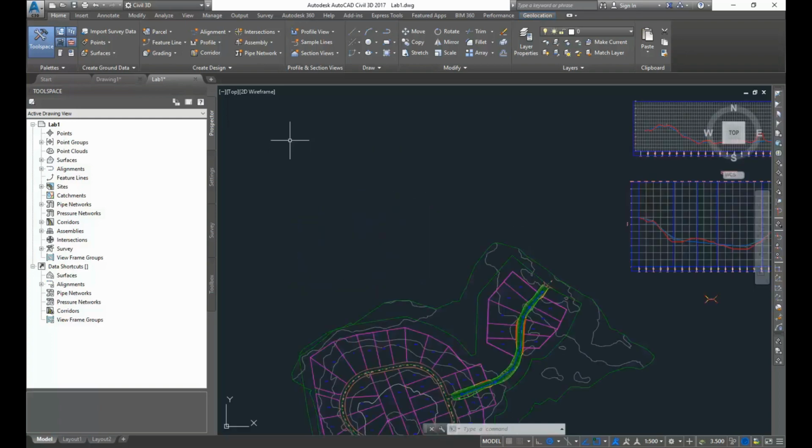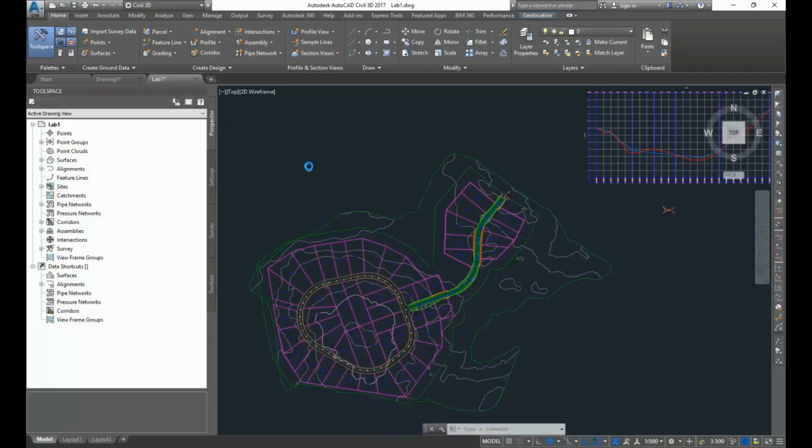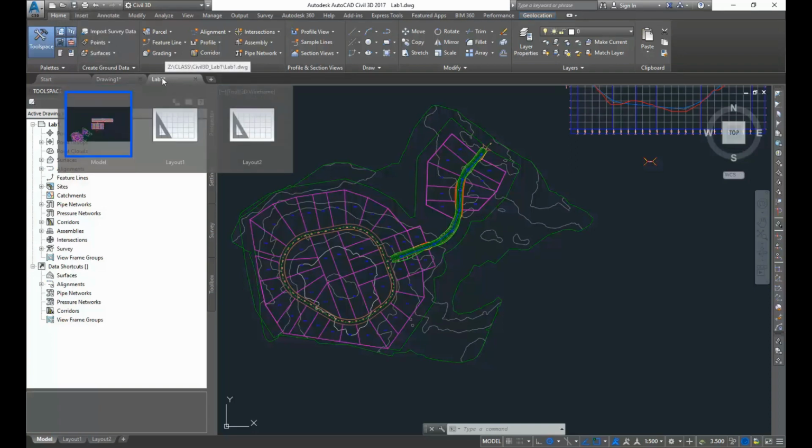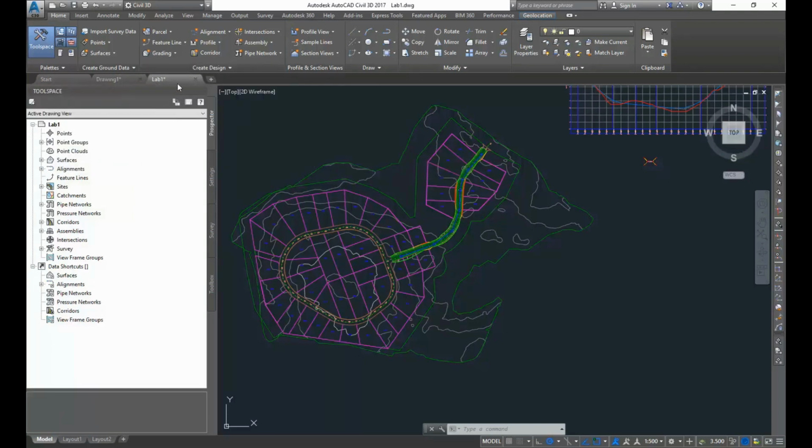One thing that's a little bit different is in MicroStation things are saved automatically. You can still undo, but as soon as you make a change, your drawing is updated. AutoCAD is the opposite: you have to save before changes are written to the hard drive. So take special care to make sure that you are saving and think about that asterisk.